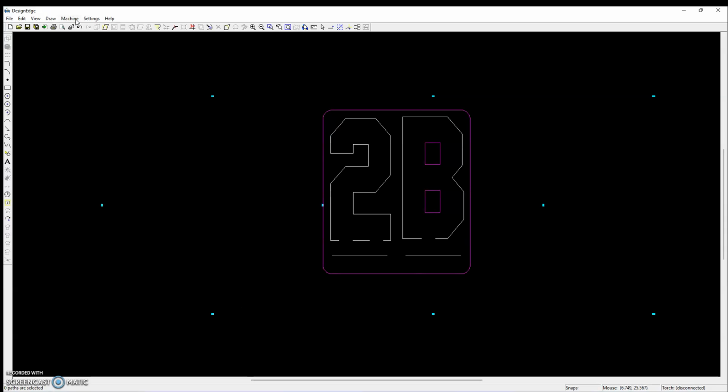And the last thing is to go to Convert Cut Path, choose the outside position of 12 o'clock on our rectangle. Make sure we're on the outside this time. We don't want to be on the inside. Make sure we're close to the line, but on the outside. Pick, convert holes to an inside path, yes. And press the Escape key.